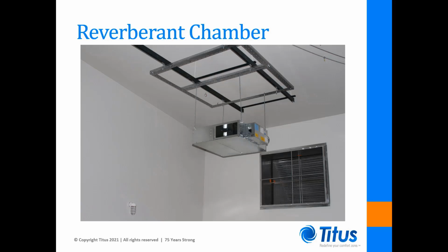The testing takes place in a reverberant chamber. This is generally a large open room that's designed for low sound absorption and high isolation. The low absorption prevents sound energy from being absorbed by the environment before it can be measured, and the high isolation provides low background sound levels. The resulting reverberant environment eliminates all directionality from sound. This allows microphones in prescribed locations to accurately measure sound pressure levels.